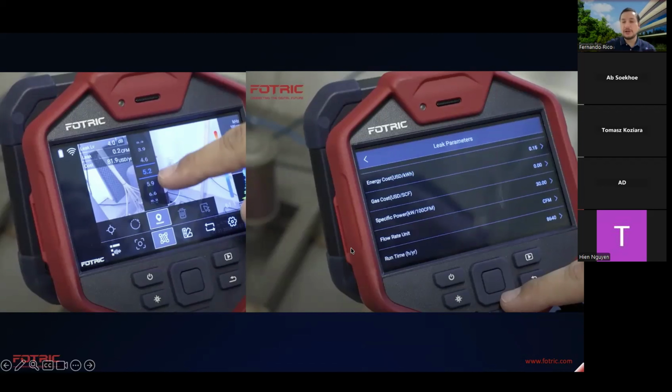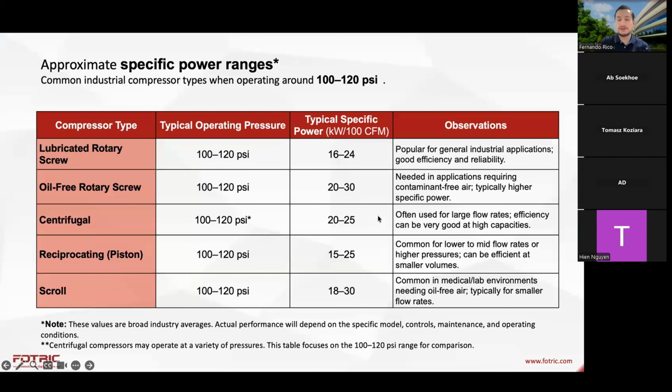So what number do I use for my specific power or the efficiency of the compressor? This is a rough idea of what different specific powers for different types of compressors are. So you see numbers anywhere from 15 all the way to 30. We typically leave it at 30. If you don't know the number, that's a good number to start.